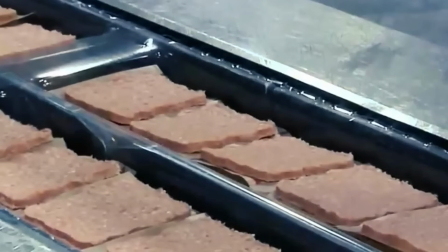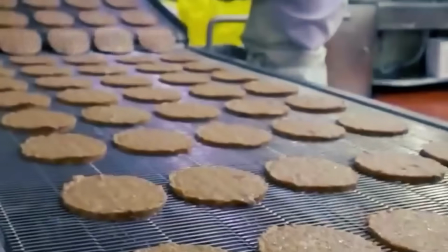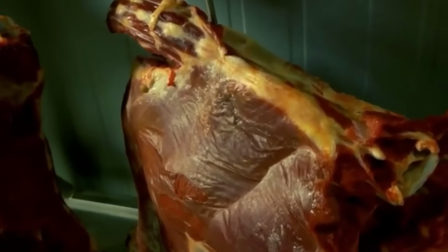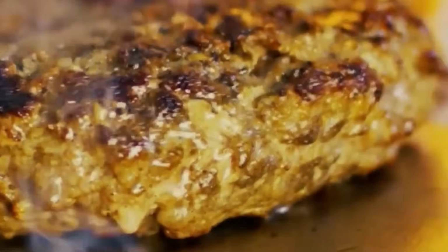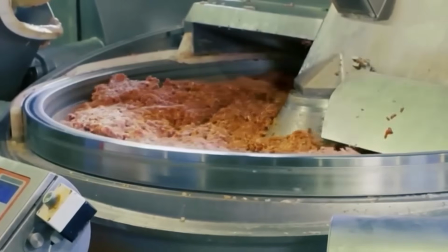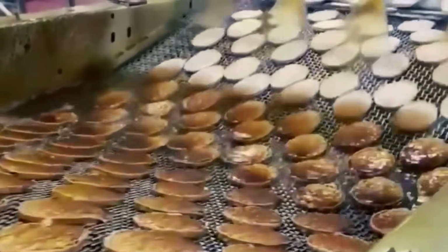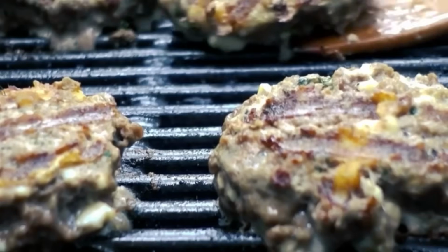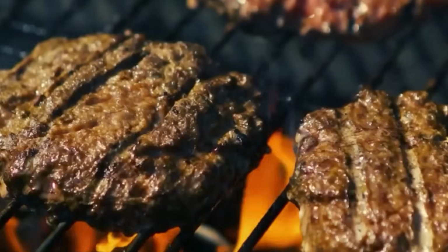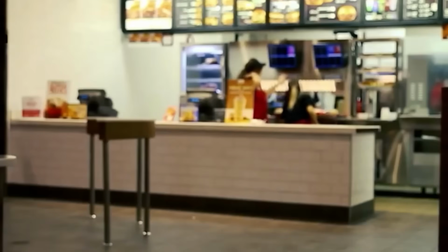While patties are cooking, buns are processed through a vertical bun toaster equipped with conveyor-style platen heaters. Buns are stored at room temperature in sealed bags until loaded into the toaster's gravity-fed chute. Each bun is sliced horizontally, and the interior face is pressed against a heated platen set to 288-293 degrees Celsius for 9 to 11 seconds, producing a lightly toasted surface that provides moisture resistance and structural stability during sandwich assembly. At the assembly station, buns are transferred to stainless steel prep surfaces.